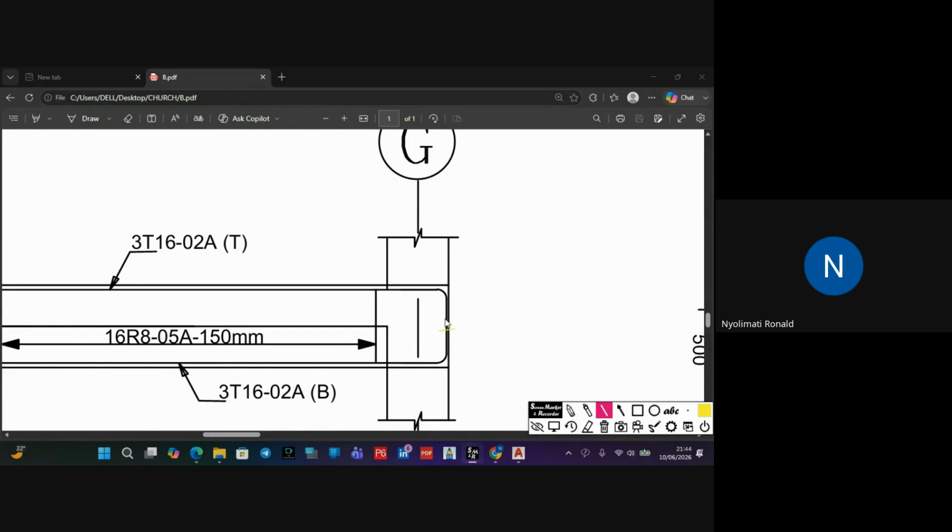Make sure you chop it here and you also chop it somewhere there. Okay? We are identifying my error together. You see? So you have to chop it there, and you also have to move it here 150, like you have seen how we have moved it there. Then you indicate here we have used the 3. You say 3 T16 bar, mark this T.